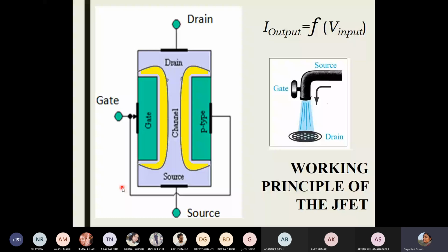So now we know that if I have an appropriate reverse bias applied to a p-n junction, we can control the width of the depletion region. And we always remember that depletion, the word comes from depleted. That means no free charges. This is a no-no zone for any free charges. So that means if you have depletion regions, so these yellow regions are depletion regions, that cannot be a path for carriers.